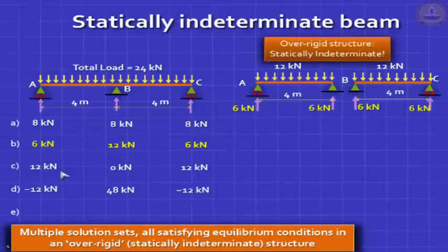So what we'll do is cut the beam in the middle and separate out the beam. Then we will find that this reaction will be equal and these two should add up to 12. But when we cut the two beams, you'll find the deflected shapes will look like this, two separate simply supported beams. And you'll find that the slope here is anti-clockwise theta, while the slope on the right side is clockwise theta, and that violates compatibility.